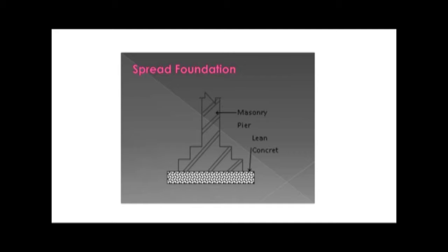And to disallow such circumstances, we use a cut-off wall. A cut-off wall is simply a wall that descends from the foundation of the raft and which breaks all the channels which may result in pulling out of the soil molecules and making the surface unstable. The safety of the foundation is further enhanced by providing rubble aprons. The rubble aprons resist and bear all the thrust and impact of the water, upstream as well as downstream to some extent.